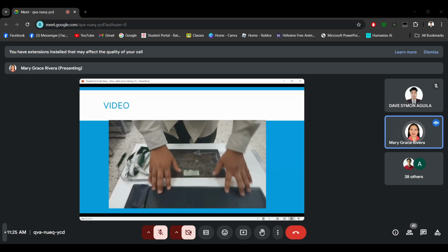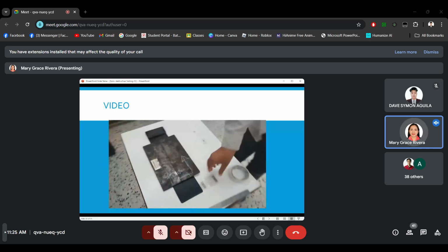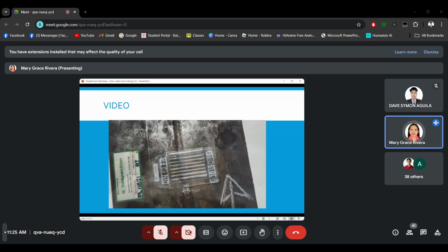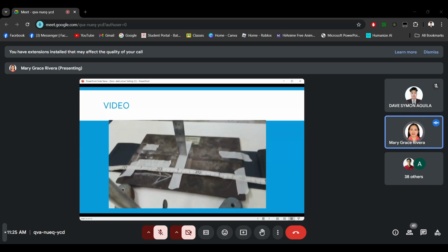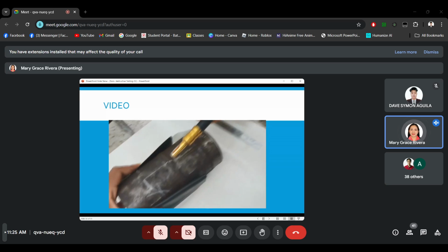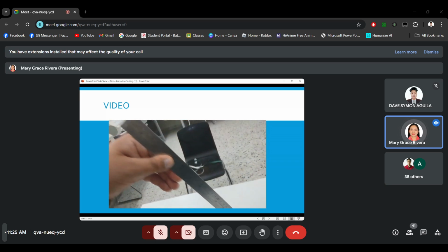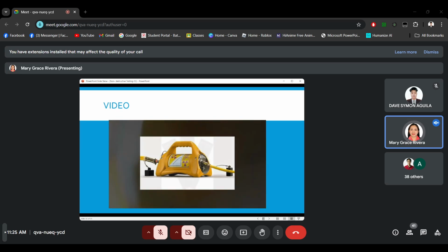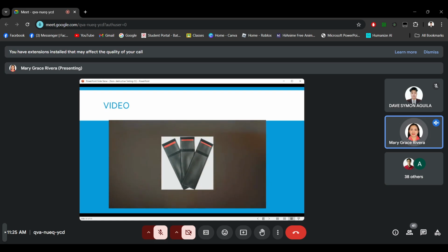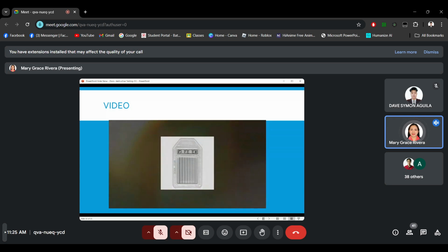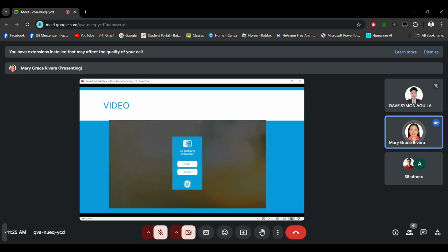This short video will show the method of radiographic testing inspection by using a gamma ray radiation source. There are a lot of techniques of RT inspection. In this short video we will show some of these techniques: single wall single image technique, panoramic technique, double wall single image technique, and double wall double image technique. The equipment and tools are the gamma ray source system, radiographic films, cassettes and intensifying screens, markers, IQI penetrometers, weld specimen, magnetic stand, safety gear, and exposure calculator.